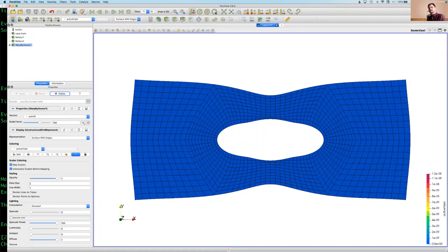Most of the solid models are implicit in Solids4foam, but I've included some explicit ones. Most of them are examples, just showing how explicit methods could be implemented. There is one I've copied in from Gibram Haider at Swansea from his PhD. He implemented a Godunov-type upwinding Lagrangian fully explicit method, similar to how, let's say, rhoCentralFoam would work. That's fully explicit, so I ported that, but he, of course, has his original repository as well, where you can directly download it. If we have time at the end, I can look at some of those cases. But in principle, it can be done.